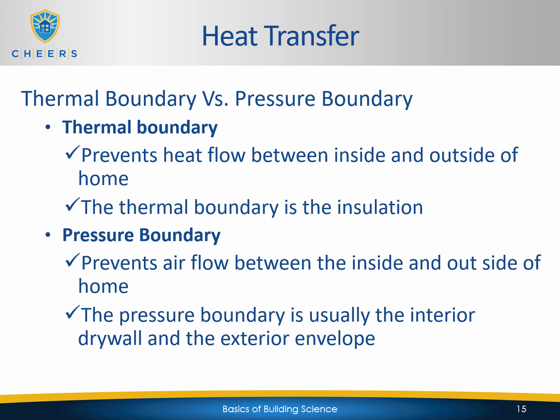One thing about the pressure boundary I want to point out is that, like I said, it's usually the interior drywall, but that's not always the case. It's a little harder to identify than the thermal boundary, because the thermal boundary, like I said, is the insulation. So you'll see it. That's obvious, right?